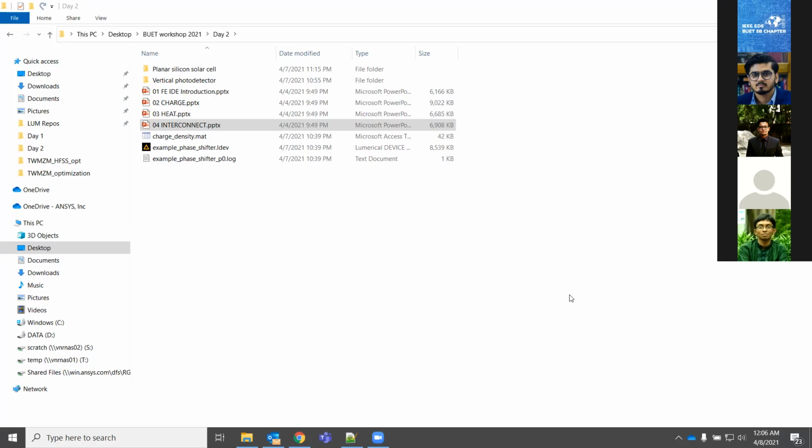In terms of optical properties, however, in FDTD you can actually model graphene. FDTD supports a particular conductive model for graphene. So at least on the optical side, graphene can be modeled, and since graphene can be modeled, you can probably do MoS2 as well. But I don't think carbon nanotube is supported. But at least the 2D materials are supported in optical simulation.